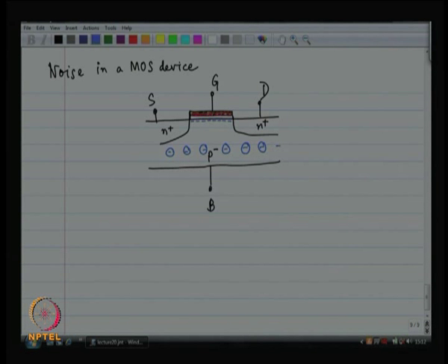Now, considering that you have only lightly doped the bulk of the MOSFET, there were not too many holes to be depleted in the first place. That is fine, life is like that. So, there are these fixed charges over the bulk of the MOSFET. These are places where the holes have gone away from, right. Now, besides these fixed charges, right underneath the gate, layer of inversion is formed. Now, what do you do with this layer of inversion? What does it remind you of?